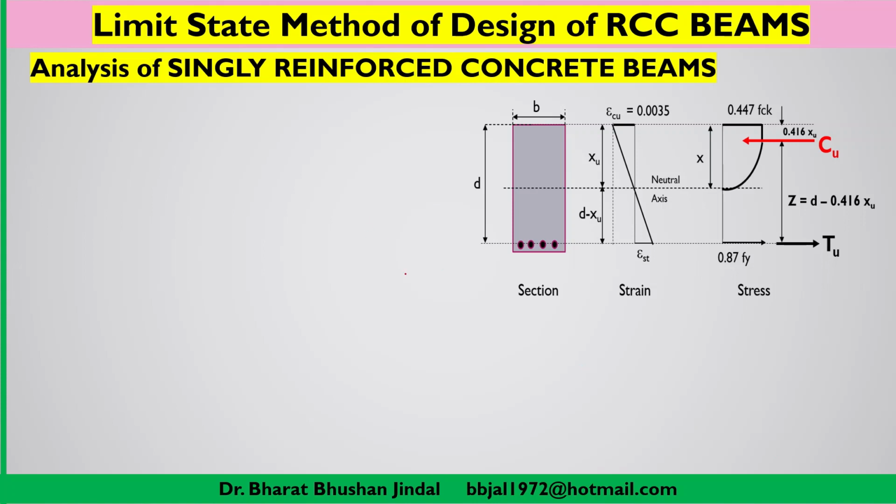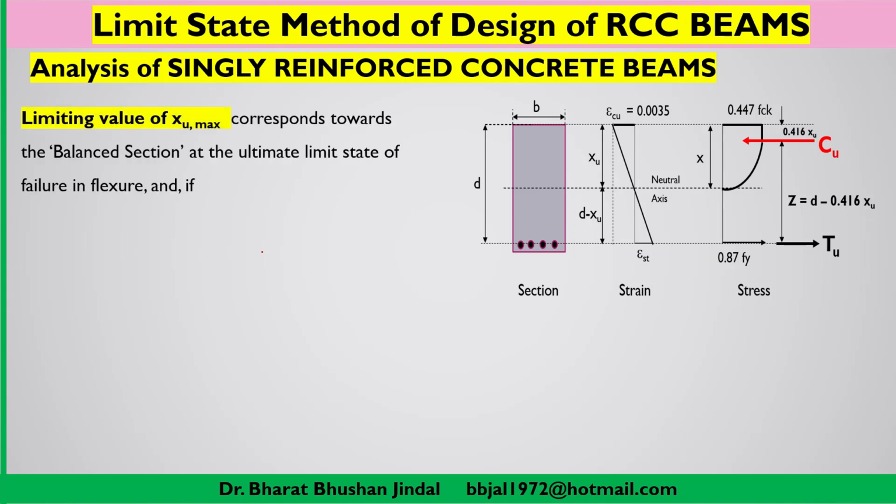Now what is basically the limiting value? Why are we taking the limiting value? So here you can note down this information. Limiting value of xu is the maximum value of the depth of the neutral axis which is restricted by IS 456, corresponding to the balanced section at the ultimate limit state of failure in flexure.